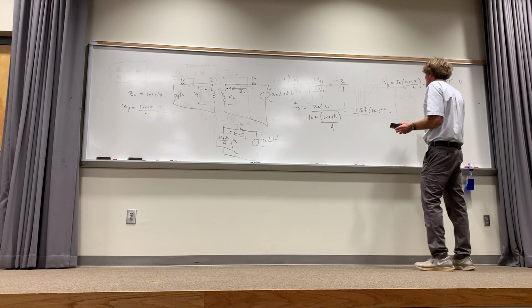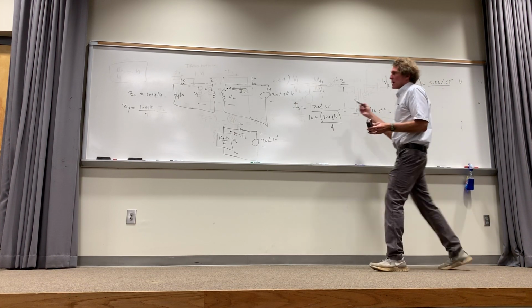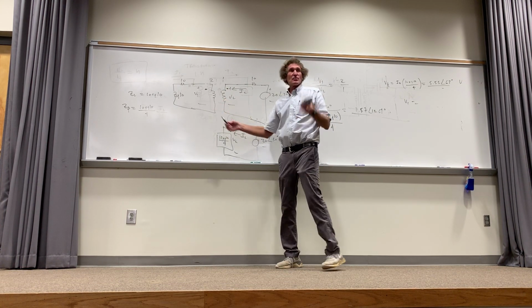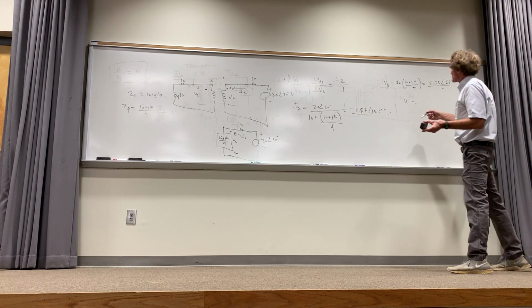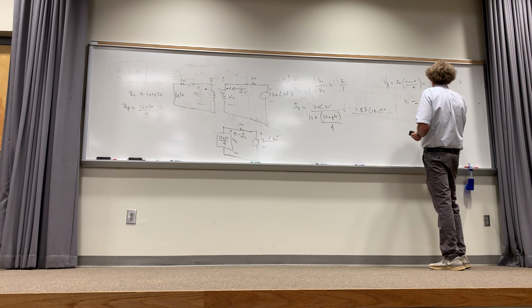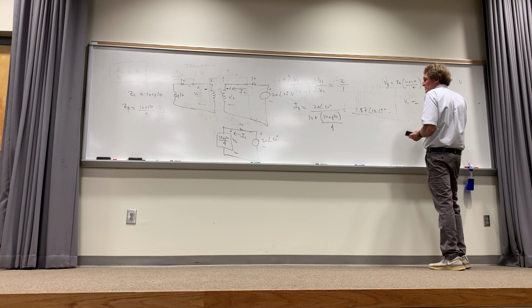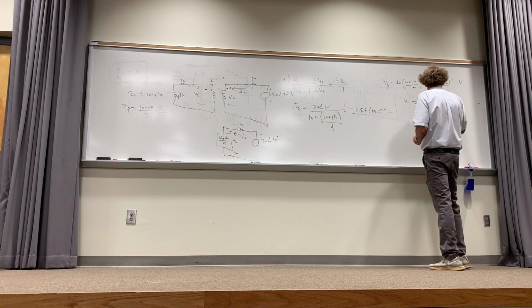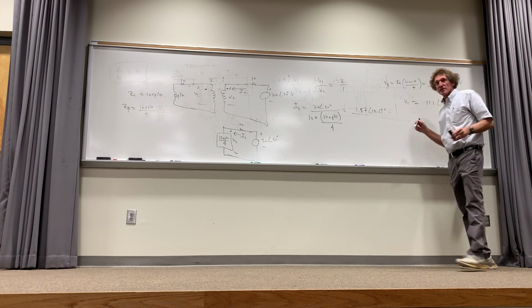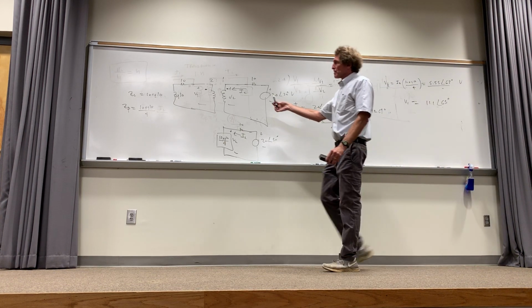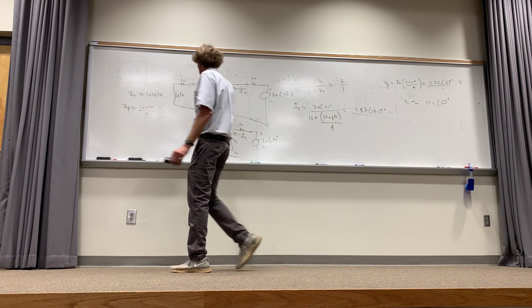What is V1 going to be, class? Just look at it. V2 to V1, it does what? Doubles, yeah, it goes up by a factor of 2. So you just take this voltage and multiply it by 2, right? And what is that going to be? That's 5.5 times 2, going to be 11 point something, right? Still at 63 degrees. Agreed, class? Everybody? You just double it.